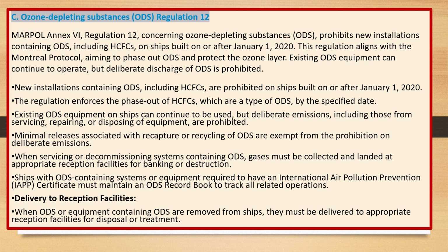Existing ODS equipment on ships can continue to be used, but deliberate emissions, including those from servicing, repairing, or disposing of equipment, are prohibited. Minimal releases associated with recapture or recycling of ODS are exempt from the prohibition on deliberate emissions. When servicing or decommissioning systems containing ODS, gases must be collected and landed at appropriate reception facilities for banking or destruction. Ships with ODS-containing systems or equipment required to have an International Air Pollution Prevention Certificate must maintain an ODS record book to track all related operations.